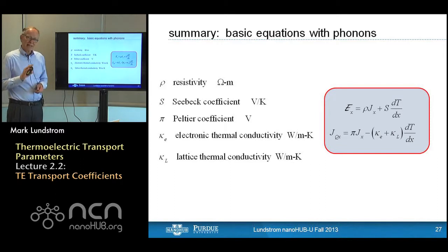It would be a good exercise for you to test your understanding. Assume the germanium is doped 10 to the 19th and run through the same set of calculations and see what the parameters are like in that case. That'll give you a good feel for how they vary with doping density.